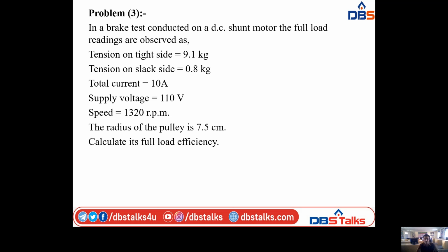So for the motor, armature copper loss, you know the formula, that is Ia square Ra. In the problem, they are given that the motor armature current is 37 amperes. Substitute here, that is 37 whole square into armature resistance they gave for the motor, that is 0.33 ohms. Finally we have the armature copper loss for the motor is 451.77 watts.